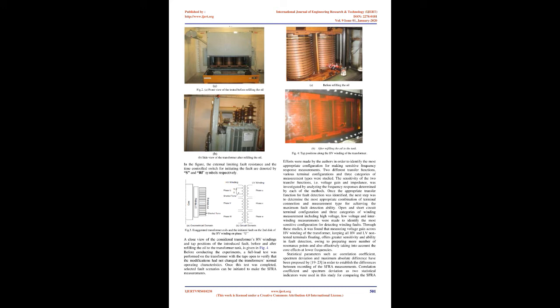In the tests carried out in this study, the measured frequency range is 100 Hz to 1 MHz with 400 frequency points per decade. The use of such a high number of points, which leads to increasing the time taken to make each measurement, is justified by the decrease in the probability of missing true resonance points and losing resolution in the approximated transfer function with the collected data points. With the used sweep settings, an SFRA scan could take a few minutes.